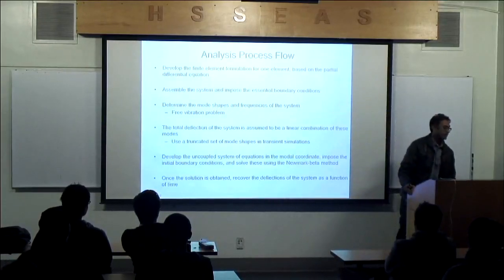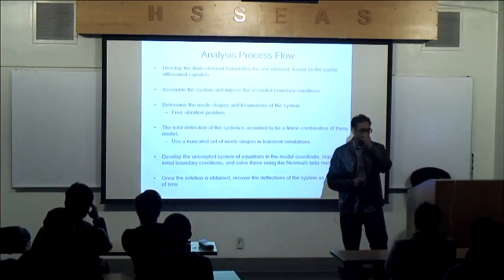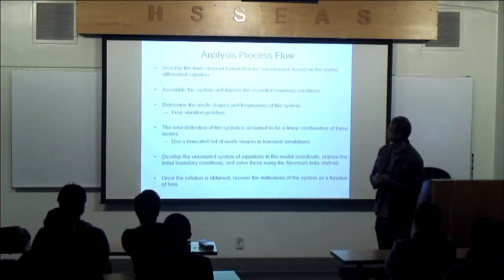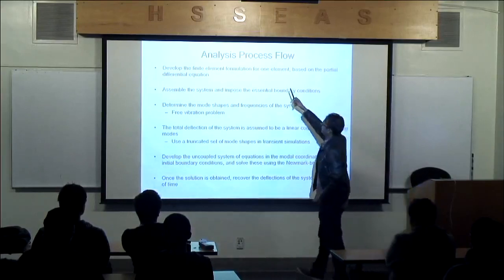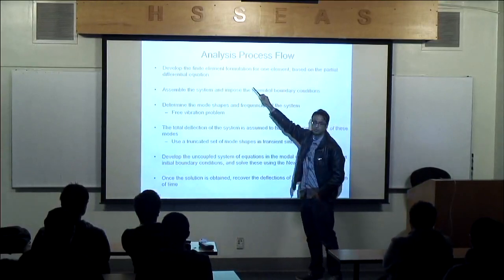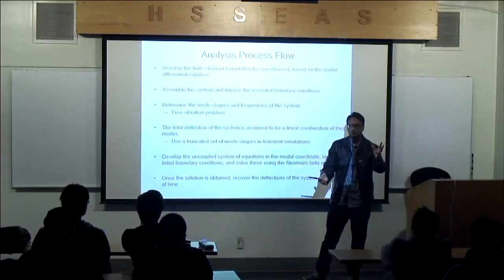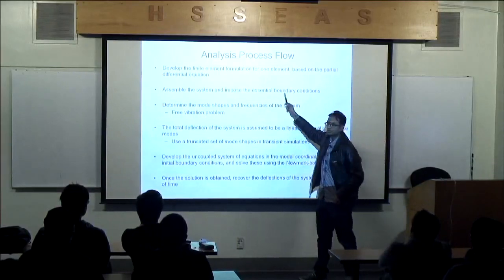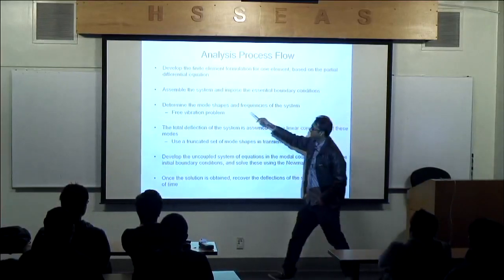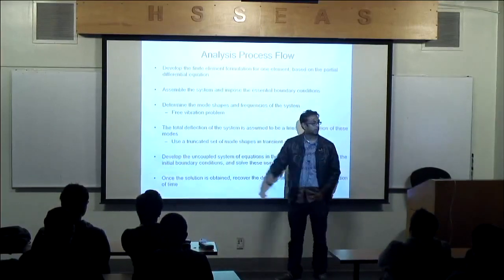Right. So what is the analysis process flow? In general, you develop the finite element formulation for one element based on the partial differential equation. Then you assemble the system of equations with the connectivity matrix. You impose the essential boundary conditions. And then you determine the mode shapes and frequencies of the system. We call this the free vibration problem.